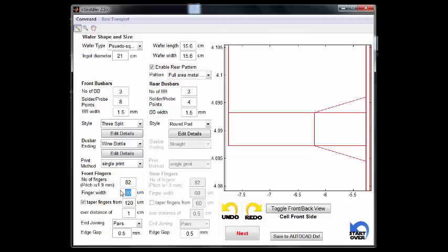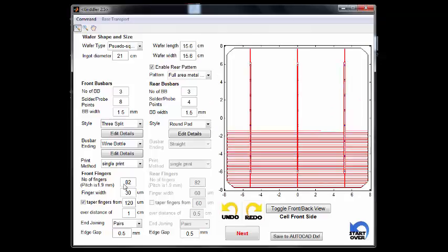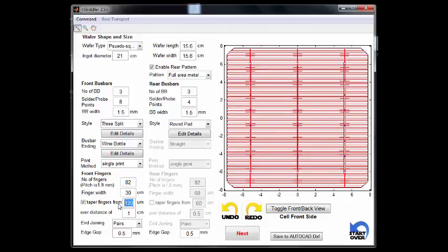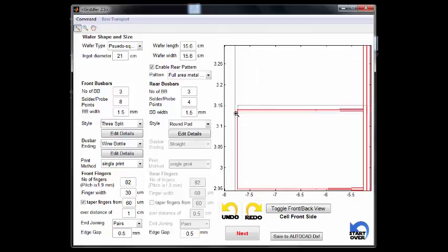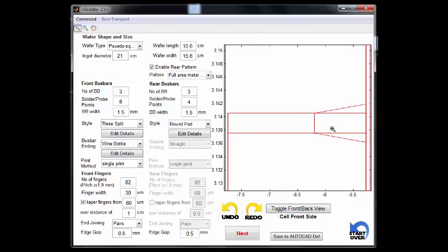For screen design, this can be particularly useful, especially if the screen finger opening is very narrow and we want to avoid finger breaks right near the bus bar. We might construct the fingers to have this kind of tapered structure.